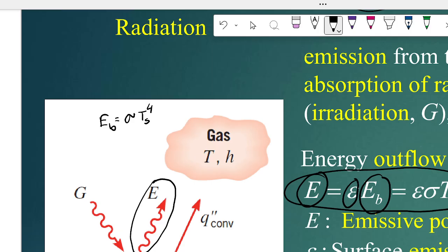But obviously, not everything is a perfectly black surface. There are lighter surfaces like here, or black surfaces like here. So what happens from the lighter surface? Obviously, you are expecting less emission. So how to quantify that? How much of the percentage of the perfect black surface is that lighter surface emitting? You understand what I just said? How much of the percentage? And that percentage is referred to by emissivity, or epsilon. Is it clear? Everybody got it? If you're following what I said?